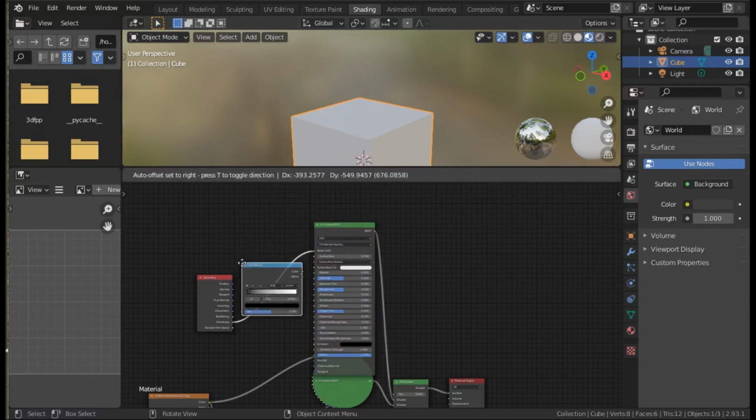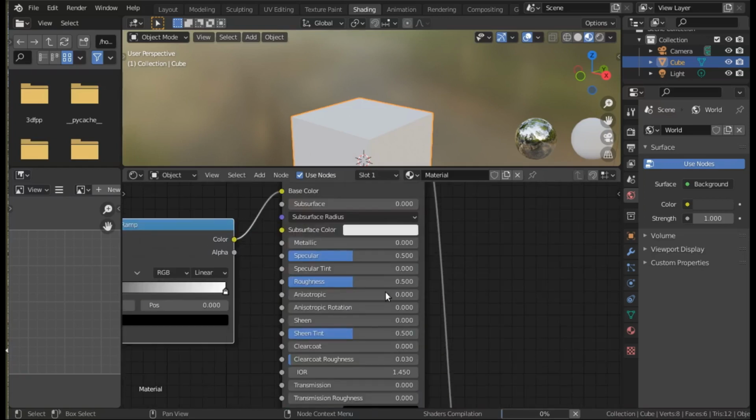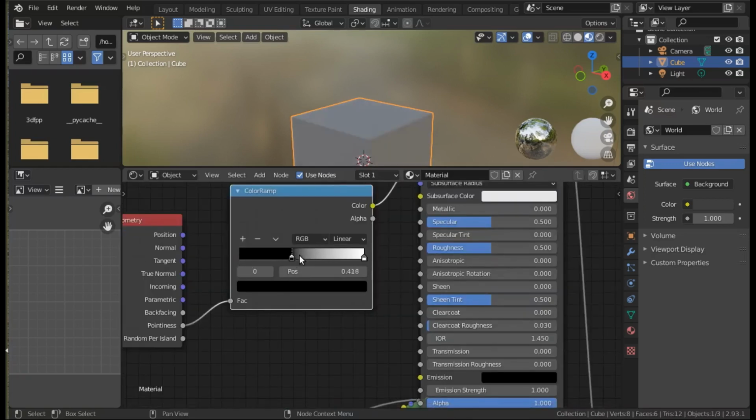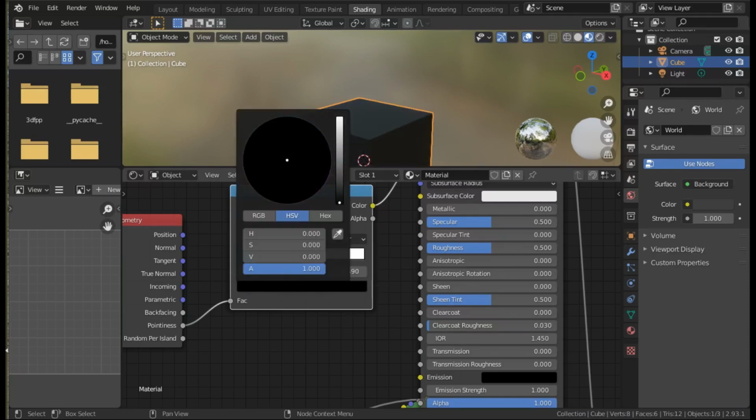The first one is we want to make the change from pointiness to non-pointiness quite sharp, so we use the colour ramp to steepen the transition. But we also want the pointiness to drop away, so we make it as a band, because basically pointiness goes from an extreme value where it's going inwards to an extreme value where it goes out, and we want the transition to happen where the material is flat.